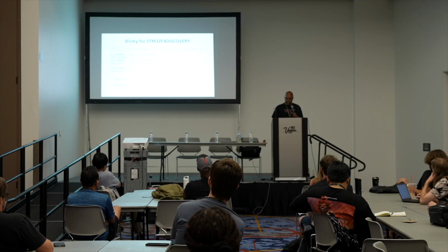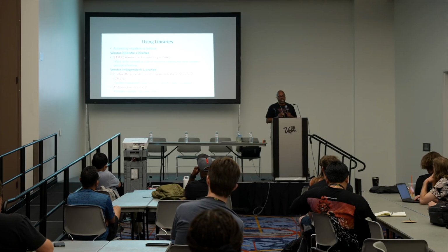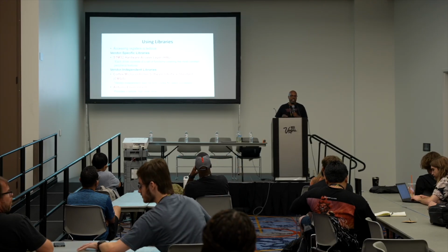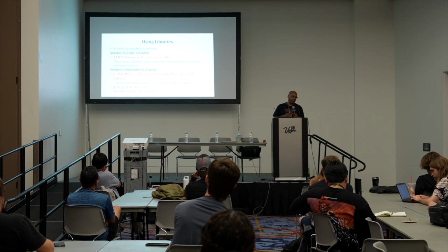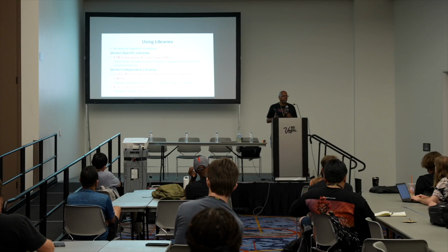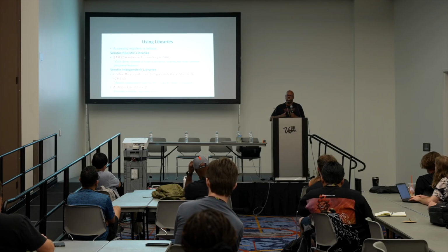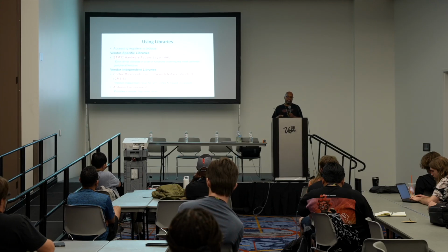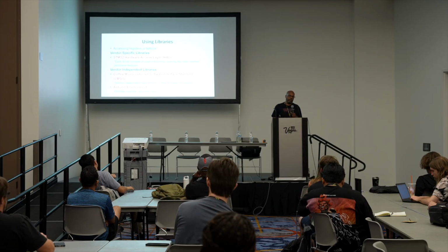Yeah, I believe it. So, okay, this is Blinky. This is sort of the most low-level type of Blinky you could write, where you directly control these registers and their values. Now, that can be tedious. A lot of times, when people make these devices, even if they're doing bare metal without an operating system, they will use libraries, so you don't have to worry about each individual register. You just call a library function and it does stuff for you. Most of the time when people make these things, they often use these libraries.